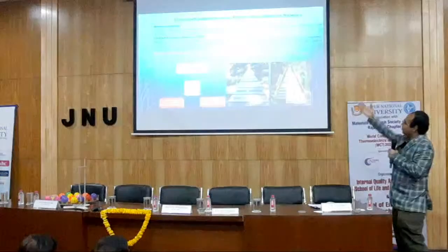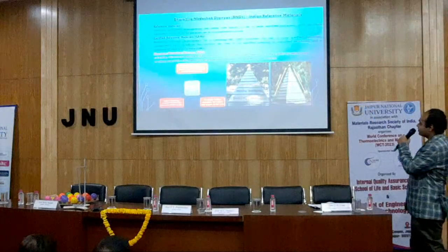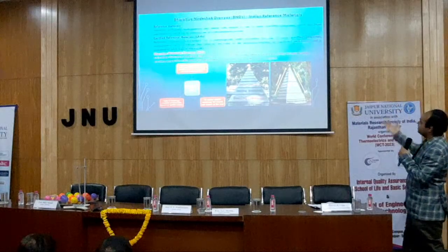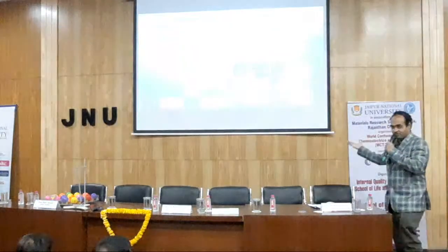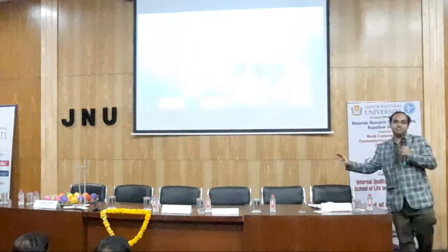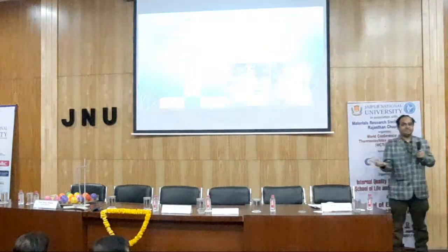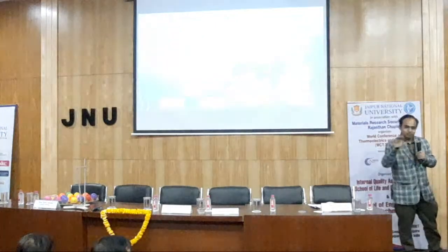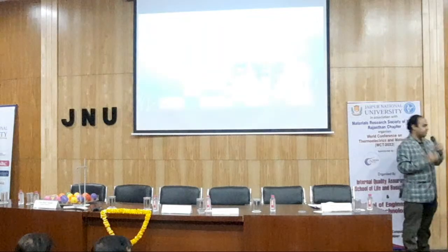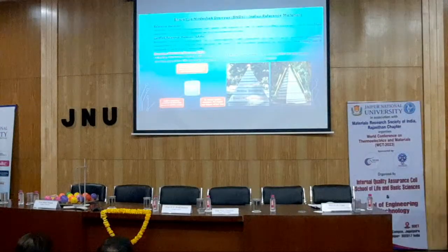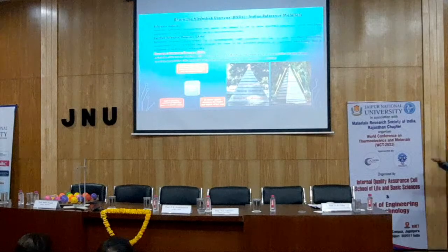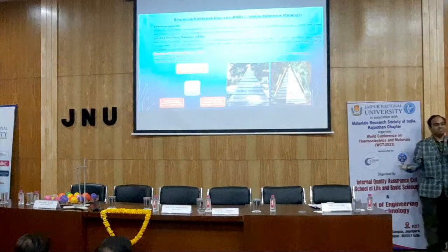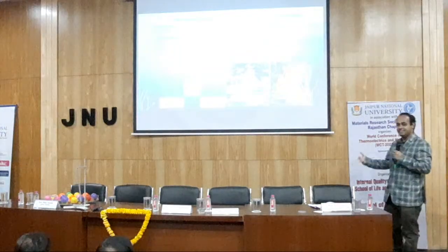Reference material is a material sufficiently homogeneous and stable with respect to one or more specified properties, which has been established to be fit for its intended use in the measurement process. So, for getting proper results out of any sophisticated instrument, it should first be calibrated using a reference material. Now, the difference between a reference material and a certified reference material is that a certified reference material is characterized by metrologically valid procedures and has a certificate of analysis with associated uncertainty.